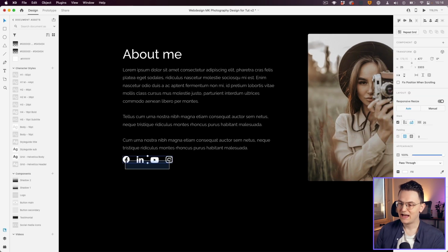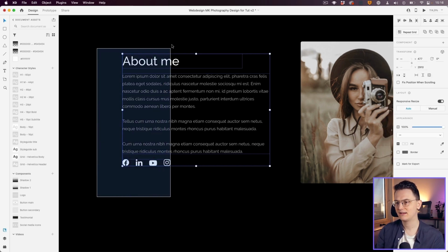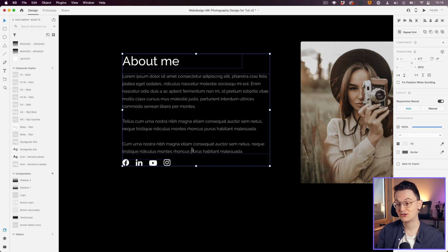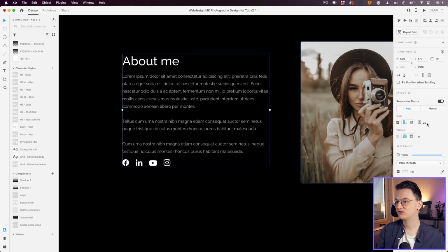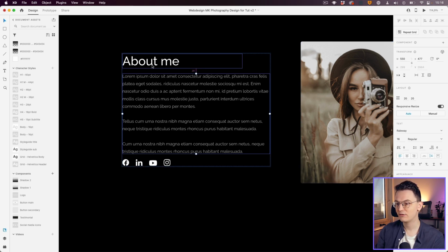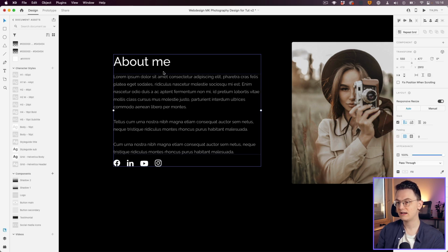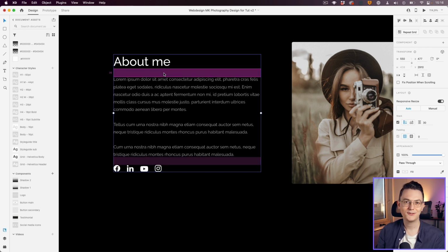So here we have used a stack, but now we can use another stack for this whole section. So let's just do that. Select all of it. Make sure always group it first. Click on stacking, there's 20 pixels between this, as you can see over here, and this. It's a little bit too small, so we click over here, we hold the wave icon, hold Shift, and then change it to 30. It's great.